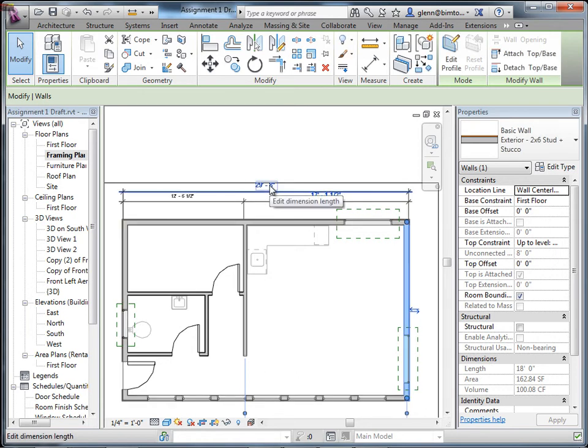Okay. What you may need to do is watch out. Sometimes there's something that says activate dimensions. If there's something that has an awful lot of dimensions on it and it doesn't want to show them all, you have to click that activate dimensions to get them to actually show up and become blue. Okay, but you can go ahead and try and drive dimensions that way.